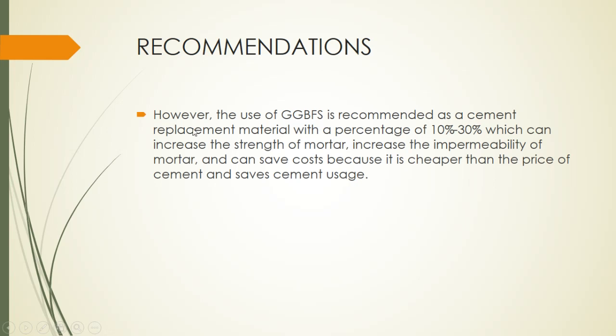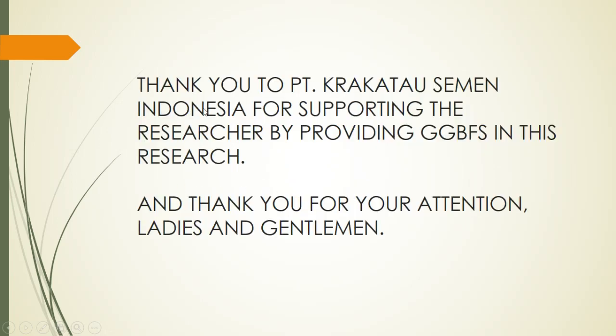Recommendation. However, the use of GGBFS is recommended as a cement replacement material with a percentage of 10% to 30%, which can increase the strength of mortar, increase the impermeability of mortar, and can save costs because it is cheaper than the price of cement and save cement usage.